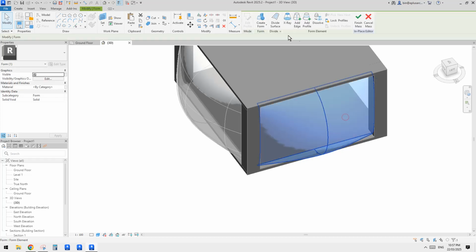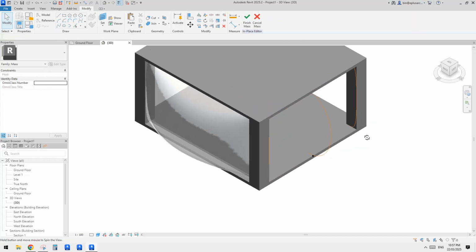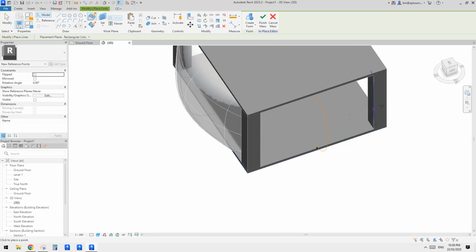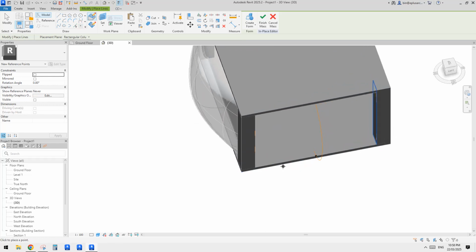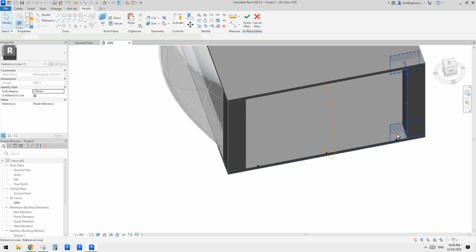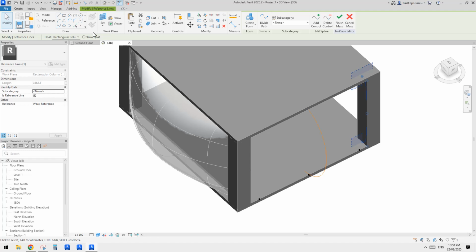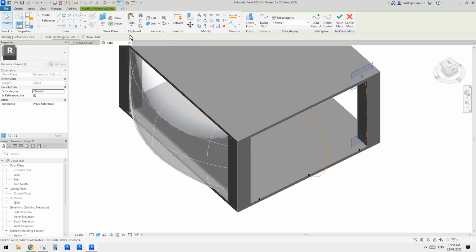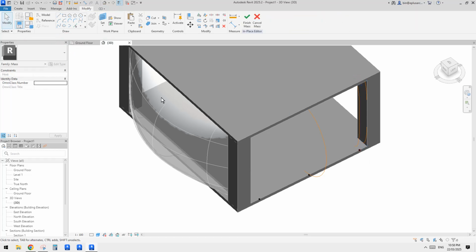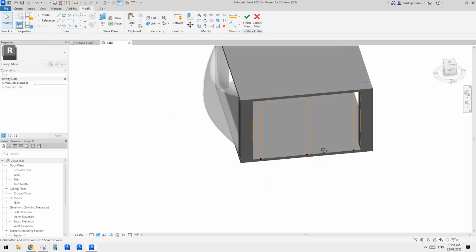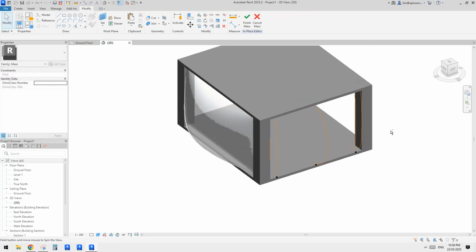So for example, let me just dissolve this one, dissolve this. So maybe I'll leave this one here, because I'll show you why I recommend you create an extrusion first. So I just place another one here, another point here, another point here. And then we still have that Control C. I think we can just paste in same place. So let's paste in same place. We have another one, and then change this one to pick onto this point, align to same place, pick onto this point. Now we have 1, 2, 3, 4, 5 profiles.